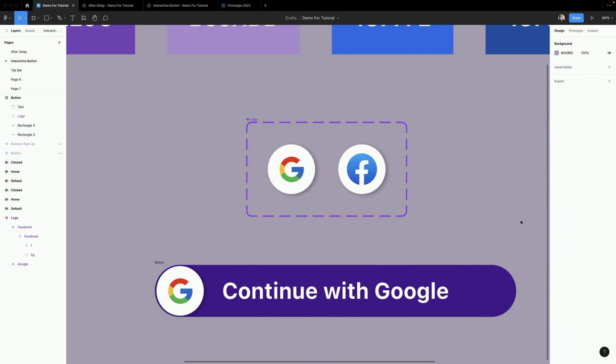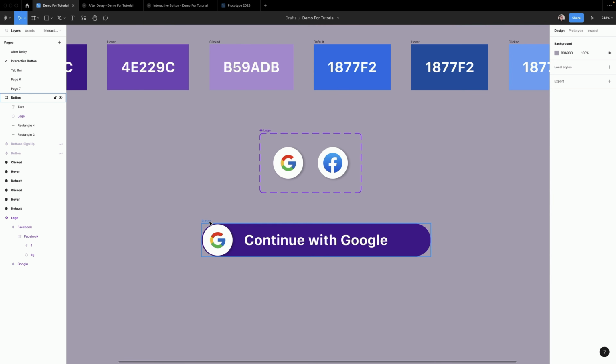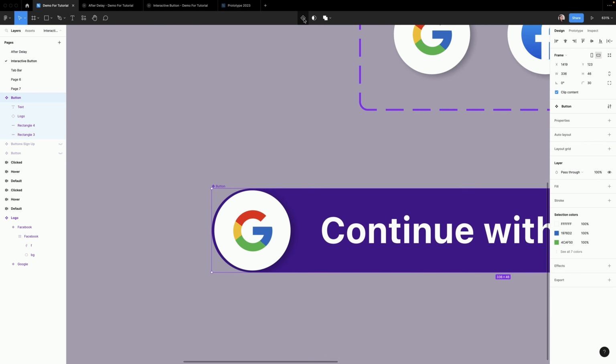Now, let's create interactive components. Interactive components enable you to create prototype interactions between variants in a component set, and they are ready to go anytime you add an instance. Create multiple instances and experiment with different behaviors all within your design. Let's create a component. So click on the 4-diamond icon, then click on Add Variant. And now a variant has been added.